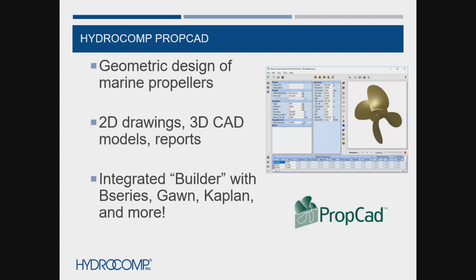Within PropCAD, we have an integrated builder that allows us to build kind of standard designs, such as the B series, the GON, Kaplan style propellers, and there's a few others such as surface piercing wedge style, thruster styles, and a few other distributions that are included in the builder. The builder allows you to build up a propeller very quickly and easily, and this is all included in the